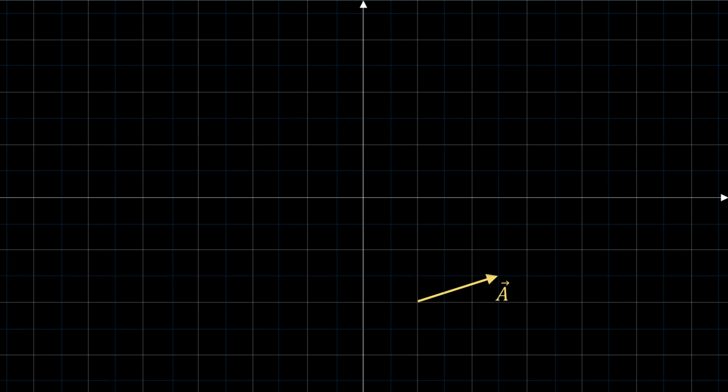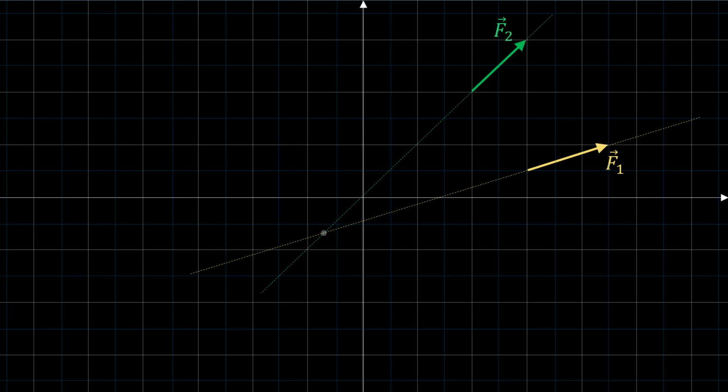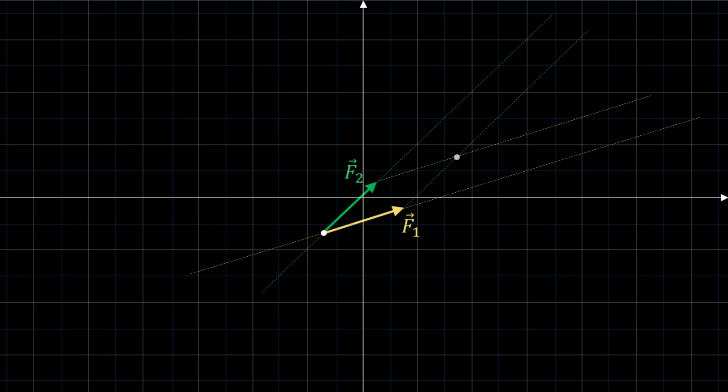That's a very good point, because again remember that all of this parallelogram rule was based on being able to move around force vectors without constraint, without worrying about their lines of action. Some of you might say, hey, hold on. You told us we can slide force vectors along their line of action. We just can't change their line of action. So here is how we add up two vectors without changing their lines of action. We slide them along their lines of action until they both have their tail on the same point. Then we use the parallelogram rule.